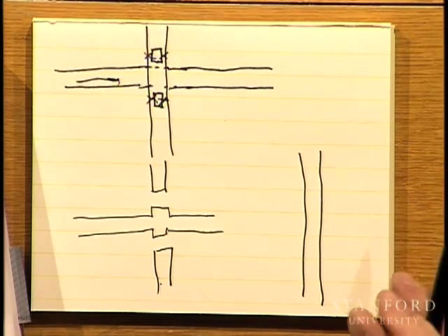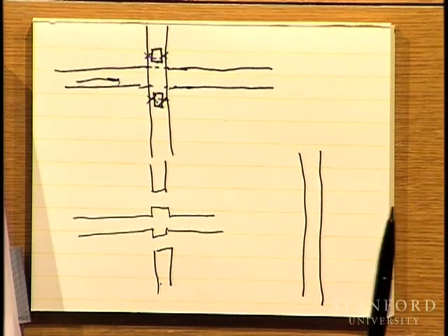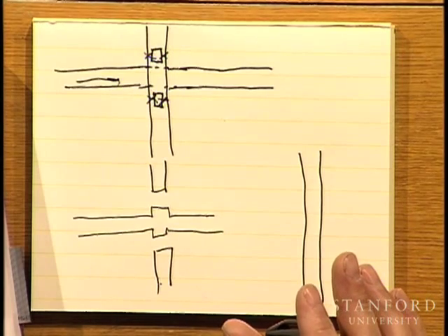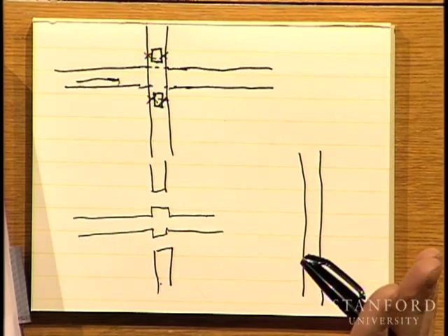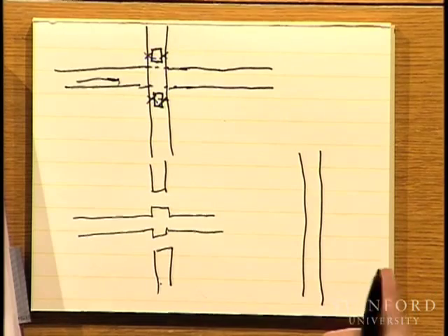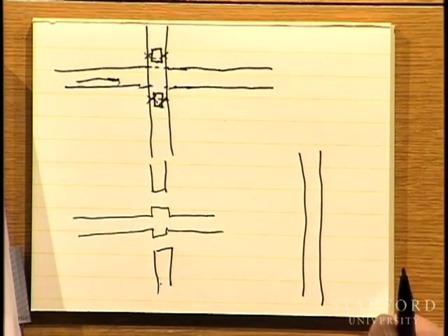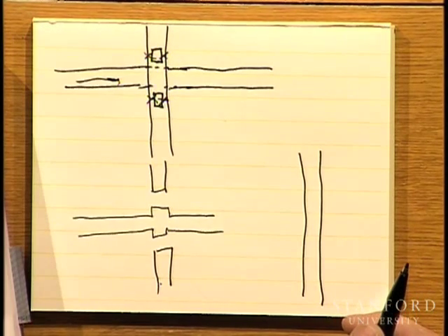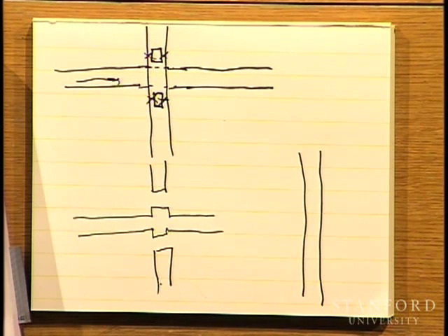It actually is a great trick because compared to any other method, even photolithography, you always have to have tolerance for misalignment, which leads to overlap capacitance and inhibits your transistor performance. We can have virtually none of that because we can use this undercut process to trim everything back to basically zero overlap, which is another benefit for high performance. Well, I tried. You're welcome to come up and visit, and we can show you more about how it actually works.